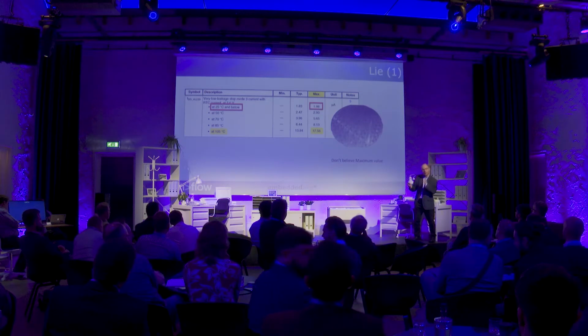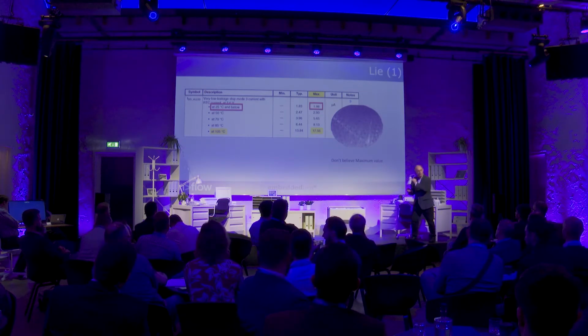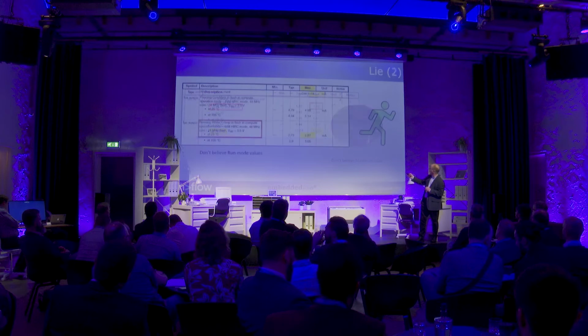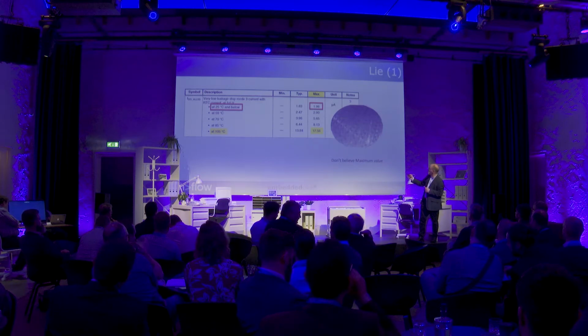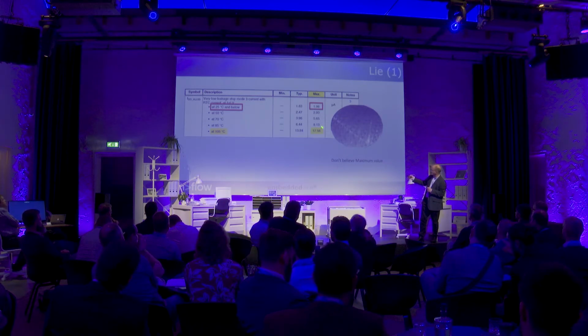If your product works at 105 degrees, speak to Tom if that's actually real for an operating temperature for a battery. And what the semiconductor vendor is going to do is they're probably going to give you some typicals, which we can ignore because they're not relevant. And they might give you this maximum figure. Well, that's just not helpful.